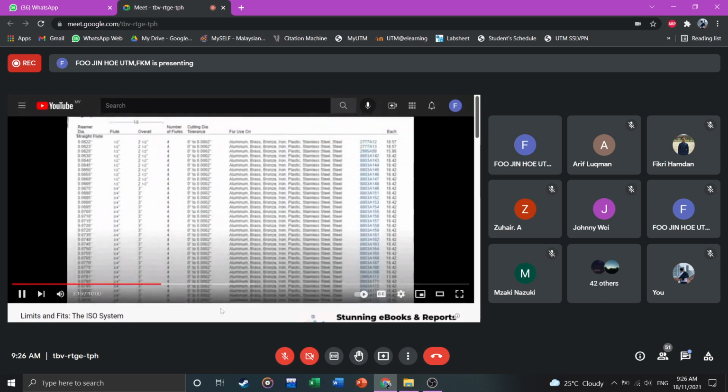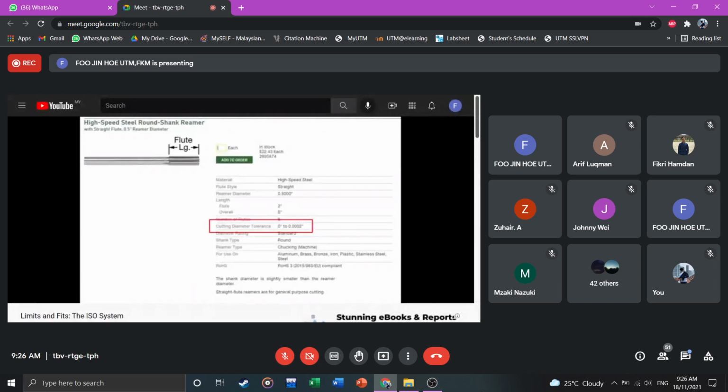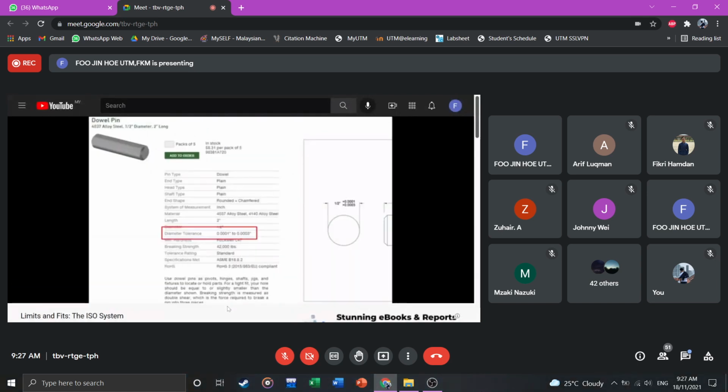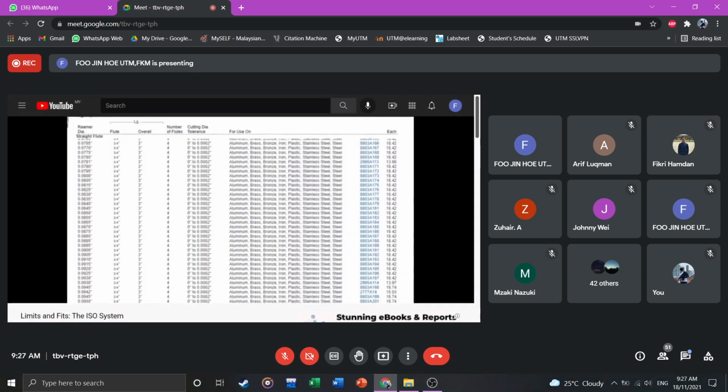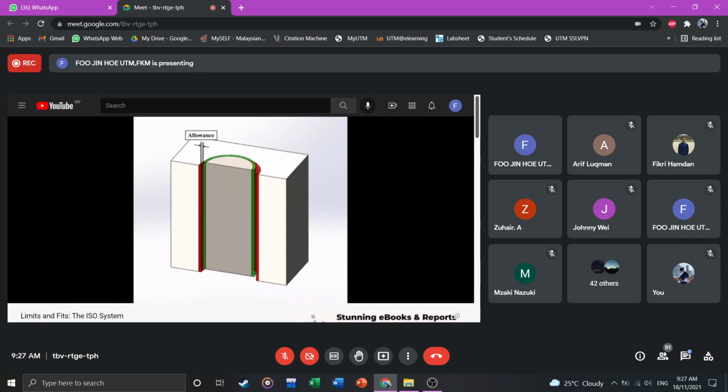So the challenge is now to decide what size reamer to use to make sure that all the dowel pins fit properly. If you know the tolerance range you can expect from your reamer, and you know the tolerances of the dowel pins, you can choose a reamer size where the smallest hole the reamer can cut still has space for the largest dowel pin. This is called the allowance, and is typically something you choose. You're allowing, say, 25 microns of space between the largest dowel pin and the smallest reamed hole.